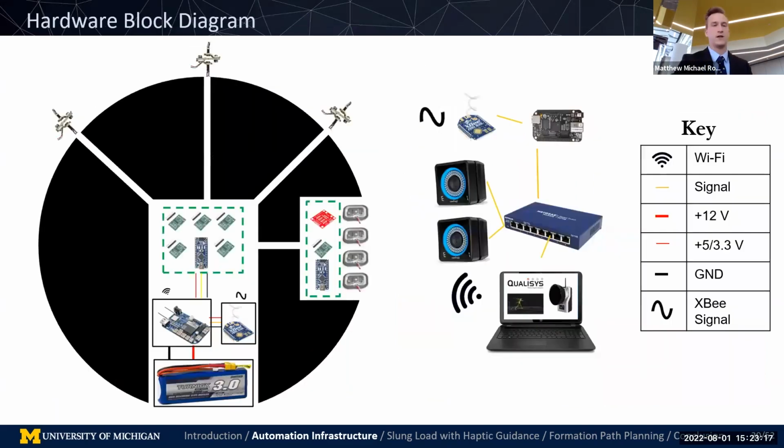Here you can see another look of it. The electronics are on the inside, so we have another BeagleBone Blue that's powered by a battery, receiving motion capture data over XBee. Then it's connected to two PCBs that are each receiving load cell tension sensor data, as well as push force sensor data, all with analog to digital converters to receive that.